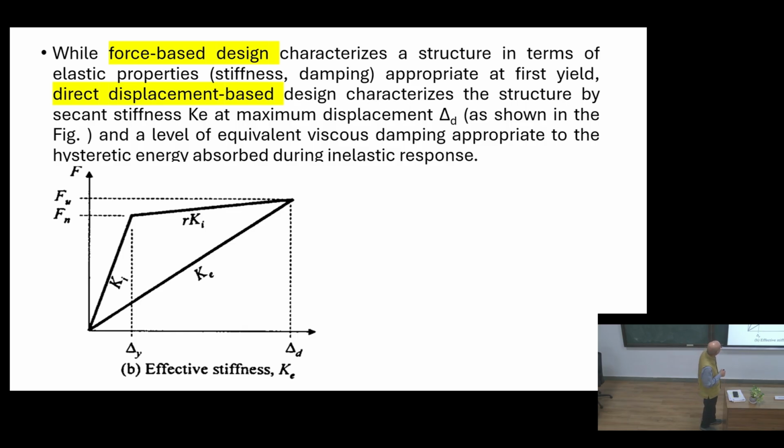While in the case of displacement design, your yielding becomes important, and the design is based on the equivalent system. This is the broad major difference between the force-based design and the displacement approach: which force displacement curve should appear, and what things contribute towards this. Next.